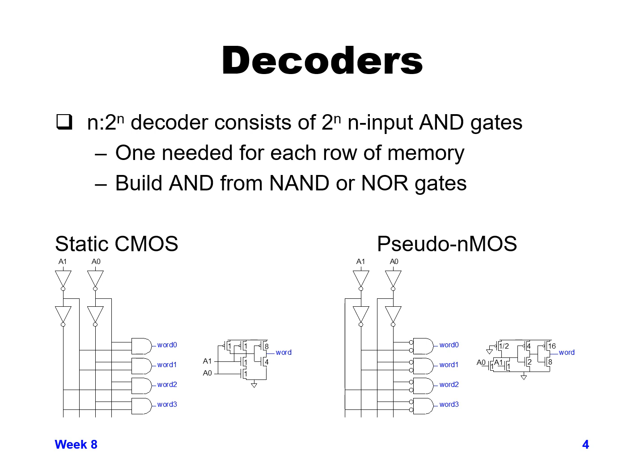Down below we've shown just 4 word lines, word 0, 1, 2, 3. In order to drive 4 word lines, we need 2 to the 2 power, so we need 2 bits coming in. A0 and A1 are bits coming in that then get decoded in order to drive the word lines. So the decoder consists of 2 to the n.